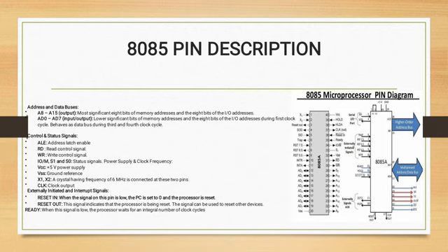Reset in and reset out are pins externally initiated by some device. Reset out is an output pin. It indicates the CPU is in reset condition, and reset in is the input pin. It resets the PC, the program counter, to 0.